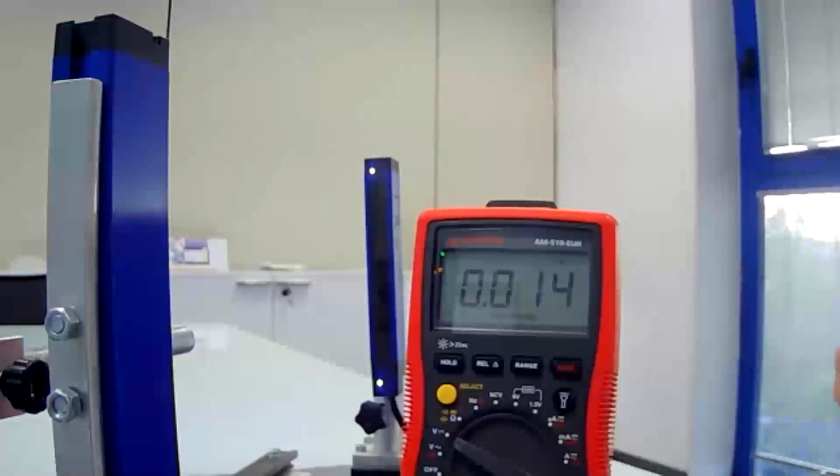So again, make the teach-in after installation and after each change in resolution. If we set the blanking function, the first thing to do is always to make a reset of the sensitivity, and so we can work. So that's all for the moment, and again I pass the speech to Giovanni.